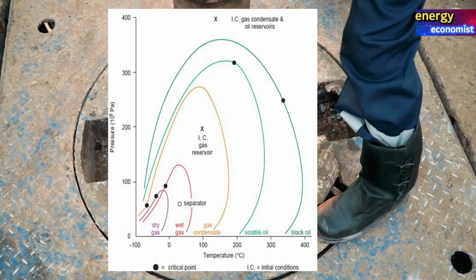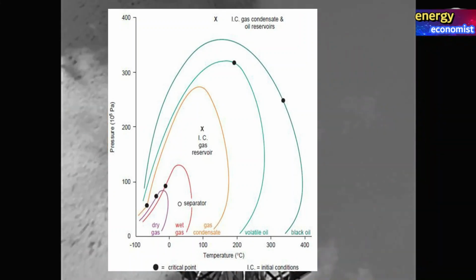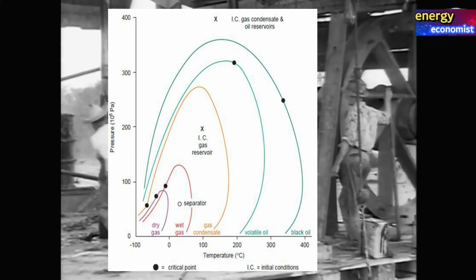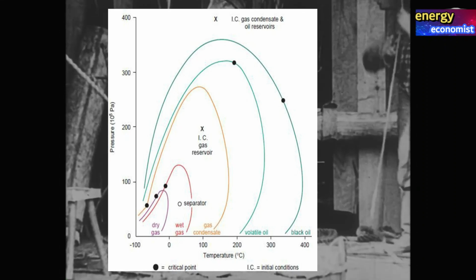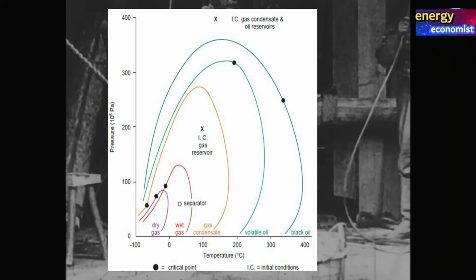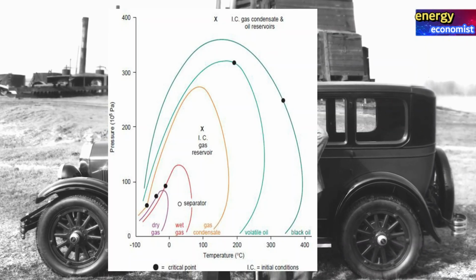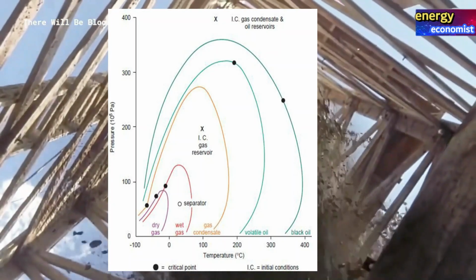An oil reservoir that exists at initial conditions with an overlying gas cap must be at the bubble point pressure at the interface between the gas and the oil, the gas-oil contact, GOC. Gas existing in an initial gas cap is called free gas, whilst the gas in solution in the oil is called dissolved or solution gas.